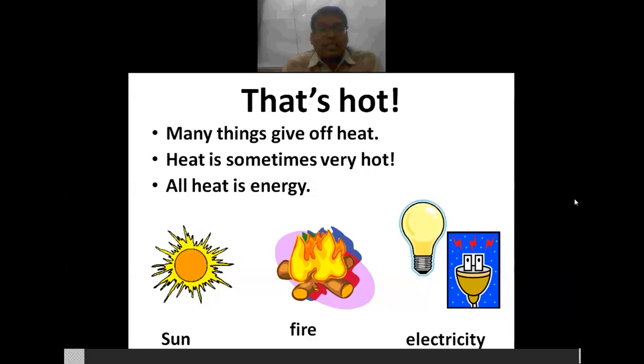Then what are the different heat duties that are associated with the process fluid? That means we have talked about the kerosene that is to be cooled from 70 degrees Celsius to 50 degrees Celsius. This is of my concern. Now what will be its flow rate? Say 10,000 kgs per hour, that is my flow rate.